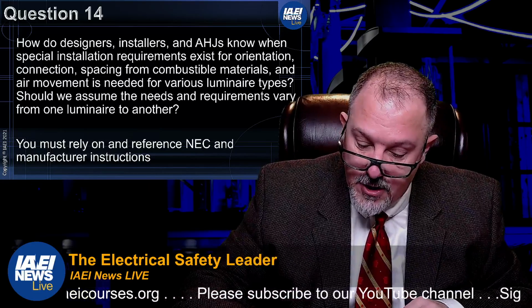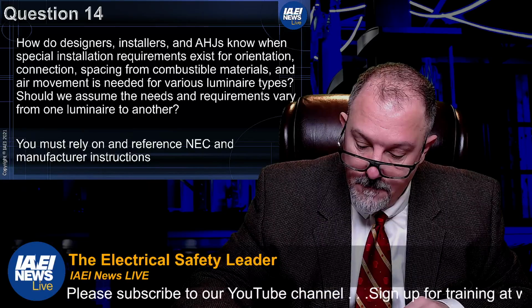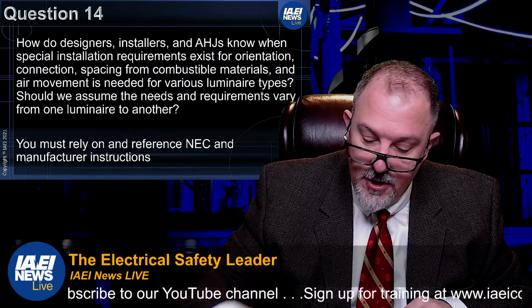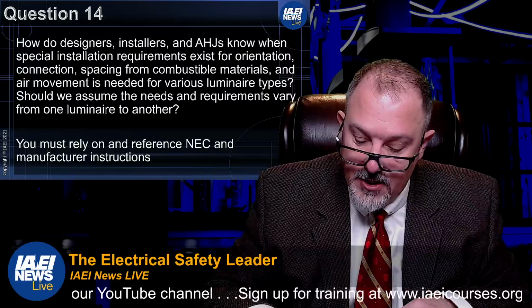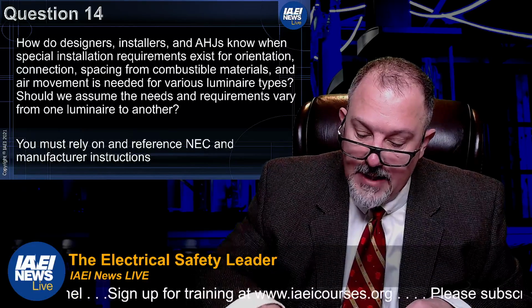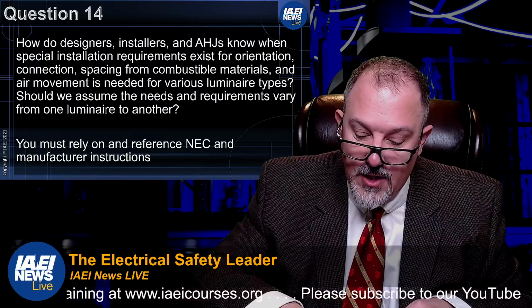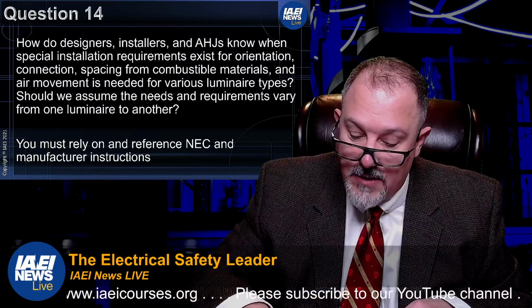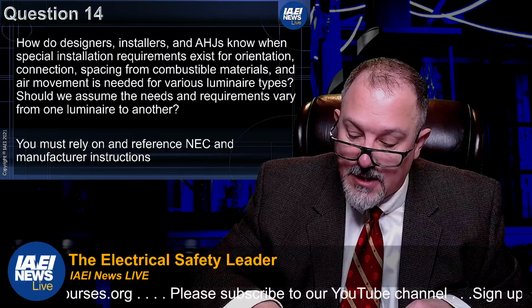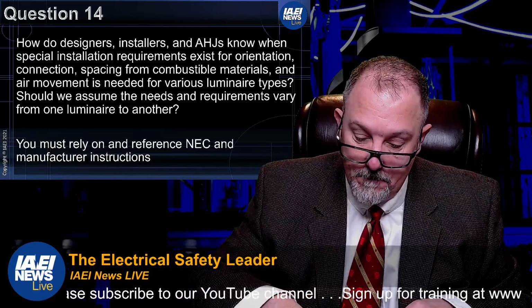High-intensity discharge lighting. You have thermal protection required for recessed remote ballasts. Thermal protection shall not be required in a recessed high-intensity luminaire whose design, construction, and thermal performance characteristics are equivalent to a thermally protected luminaire and are identified as inherently protected.